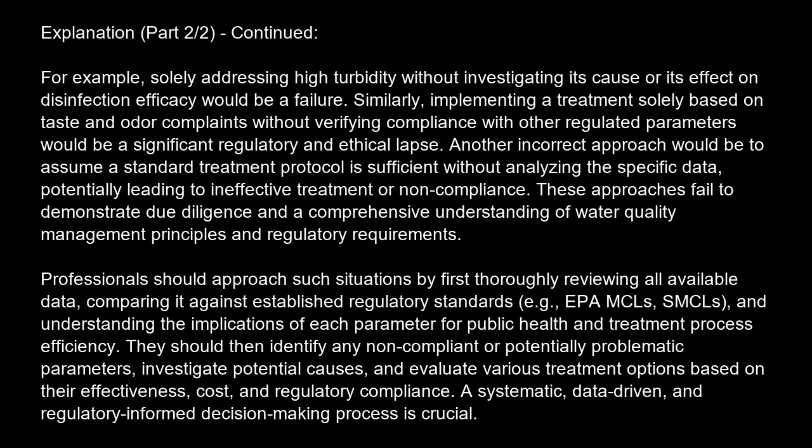and regulatory requirements. Professionals should approach such situations by first thoroughly reviewing all available data, comparing it against established regulatory standards, e.g., EPA MCL, SMCL, and understanding the implications of each parameter for public health and treatment process efficiency. They should then identify any non-compliant or potentially problematic parameters, investigate potential causes, and evaluate various treatment options based on their effectiveness, cost, and regulatory compliance. A systematic, data-driven, and regulatory-informed decision-making process is crucial.